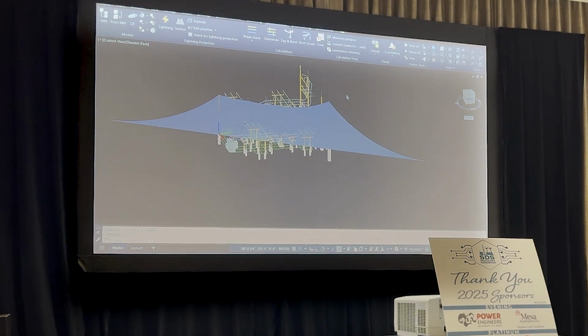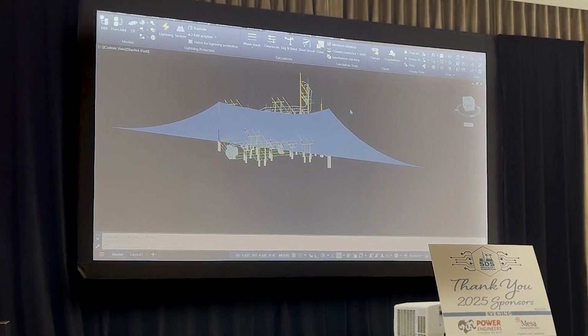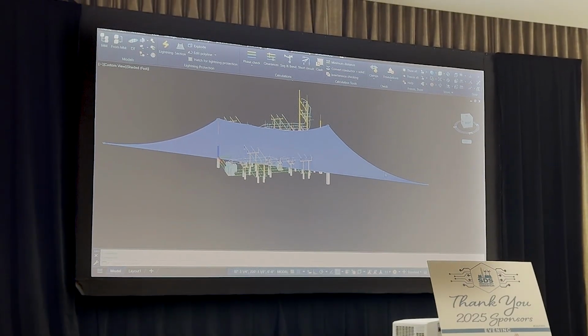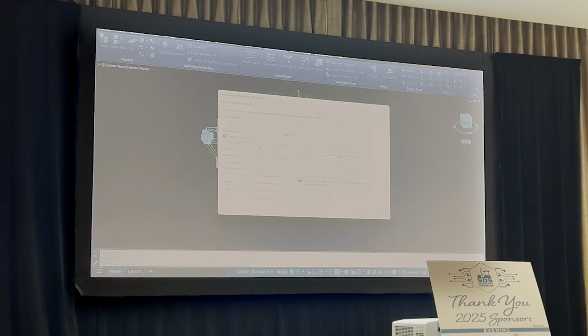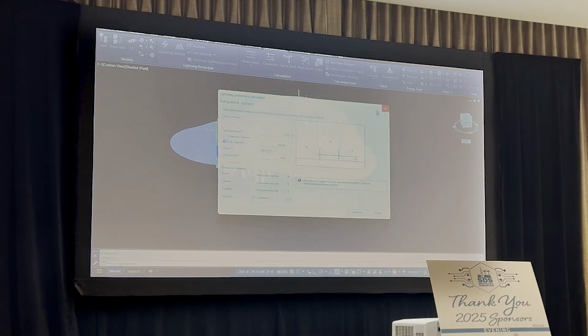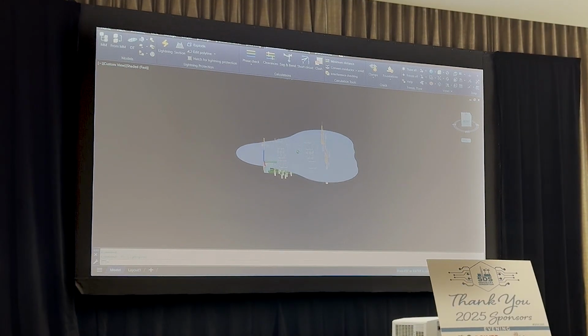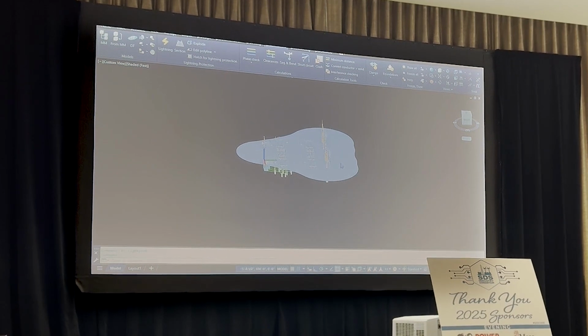And what that does is it gives you a cross section across what that area just was, right? Now it looks very similar to what this does if I say protection height. So if I say protection height, you just run it 200 inches. It does the same type of thing, but vertically, right? And it has tools for you to be able to hash these too, to be able to create those lighting protection drawings that show your coverage at different heights.